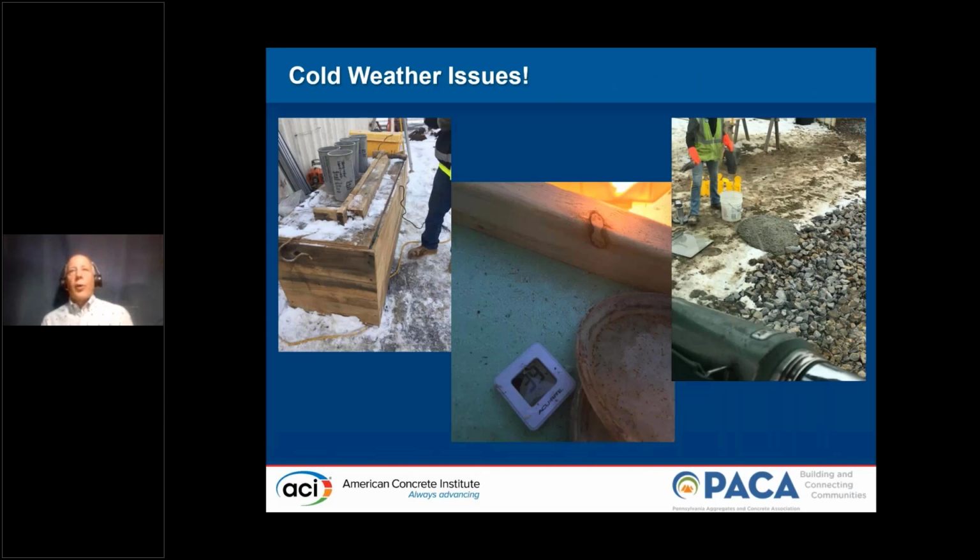This is not just a warm weather problem. Project in central Pennsylvania in January, disputes for months over quality of concrete. The breaks were coming back all over the place. But they said, well, we got a heated curing box, so we don't think that's the issue. I said, okay, do me a favor, right before you put the cylinders in there, grab a picture of a temperature for me. It was 39 degrees. And we saw what happens on the upper side. If we go on the lower side, boy, are we gonna affect the strength of that concrete. So fortunately, with this information in hand, producer got to the construction management team and the problems were resolved. And everything since then broke correctly.